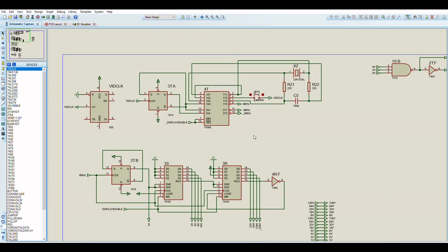So what we have first of all is some analog circuitry here for generating an approximately 12 megahertz clock, using a crystal and a couple of resistors and a nice capacitor. And this is jumpered, so it allows me to either select the clock crystal output, or we can use here a CAN oscillator. In the built boards, it uses the clock crystal arrangement. And actually I've tested this and it works really well.